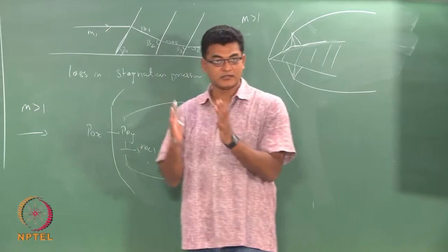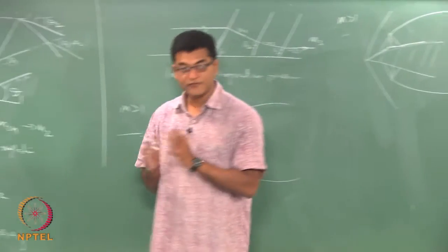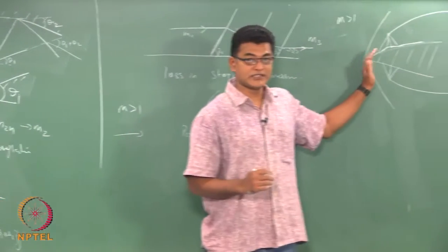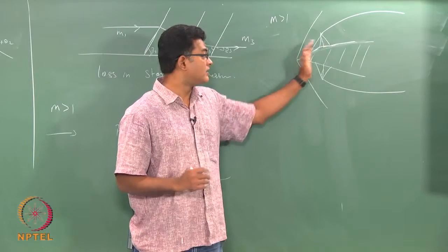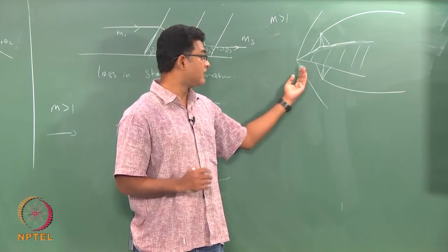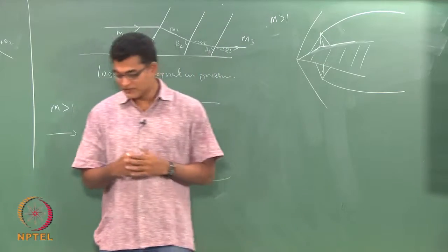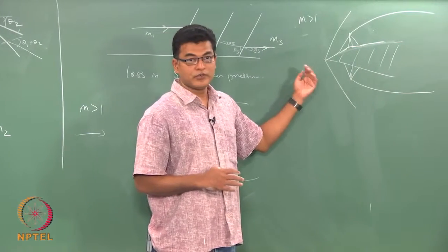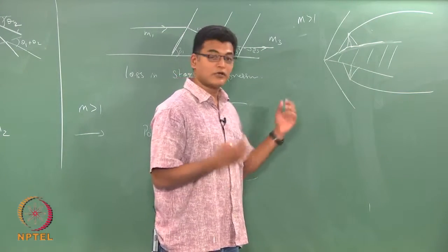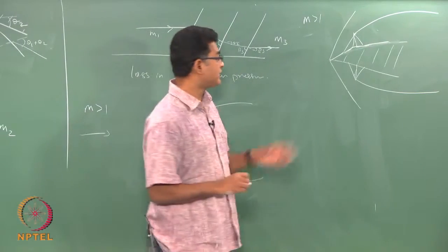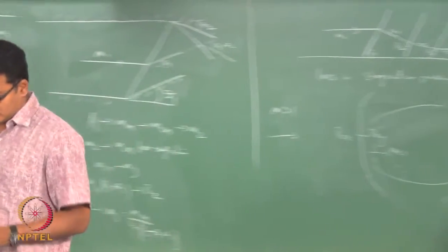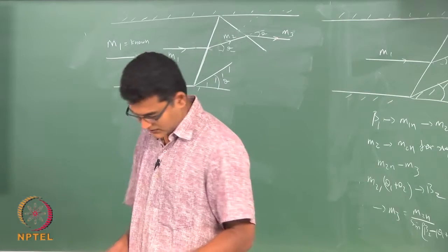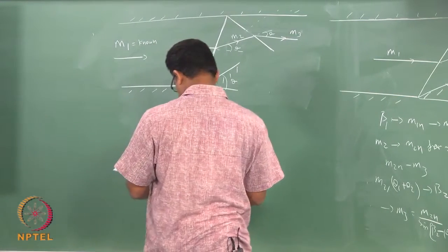So, P0 is the total pressure, an indication of how much work the flow can do. So, you want to maximize that and you want to gain compression inside the diffuser as much as possible. Now, in a compression shock wave you are actually compressing, you are increasing your pressure. So, you want to gain that, you want to do that here, yet you do not want to lose your P0x or the stagnation pressure. So, you can do that in a numerical problem here. So, let us try to work it out.